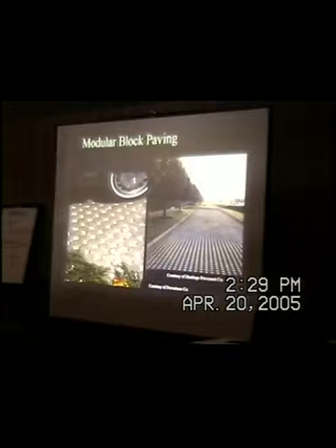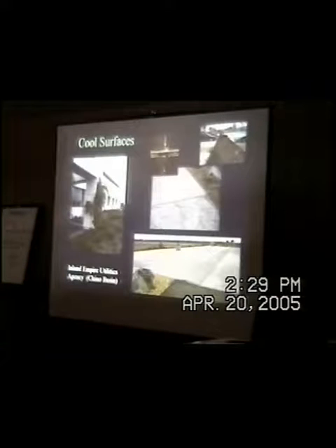The permeable paving systems to get the water to perk in right on the street. This is one of my favorites. This is a brand new facility. This is conventional concrete, and this is no rebar, pour about twice as thick, get rid of most of the fines, so you've got something like that popcorn that sticks together, and the water literally drops right through it. This is a thin section, but their sections are thick, and they love to go out there now. The maintenance guys for the facility, this is a water agency, were very skeptical.